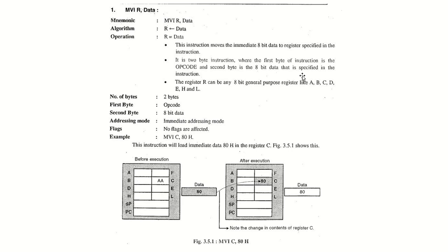Most of the instructions we are going to discuss today will be following either the immediate addressing mode or any of the modes which we have discussed today, right? We have discussed five: immediate, register, direct, indirect, and implied. So it's following immediate, and it's not affecting any flags. I will discuss with you whenever we get an instruction that affects the flags.